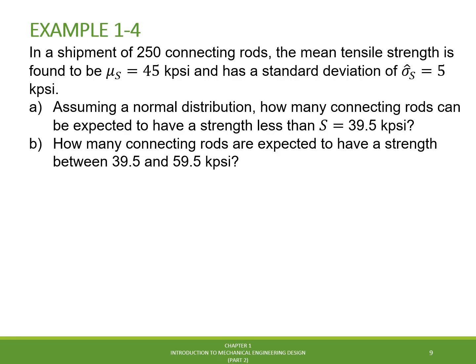59.5 kpsi? So this is a problem in which, from the batch of identical connecting rods, we are able to apply some statistics to measure the tensile strength of each one of the connecting rods, and then we calculated the average or the mean and the standard deviation. And then we are interested in applying the statistics through the NORM.DIST function for the limit between 39.5 and